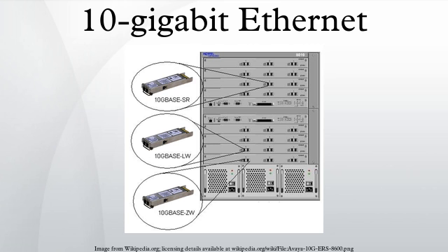SFP+ Direct Attach today is tremendously popular, with more ports installed than 10GBASE-SR. Backplane Ethernet, also known by its task force name 802.3ap, is used in backplane applications such as blade servers and modular routers and switches with upgradable line cards.